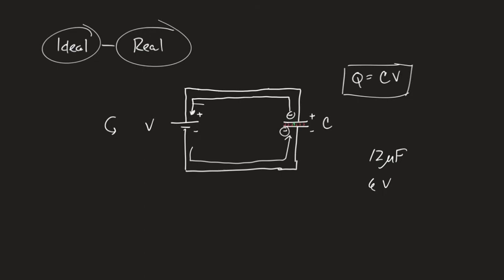Is it blue because of the chemical burning? Yeah. Generally. And the dielectrics that they tend to fill these with and the electrolytes that they fill these with are toxic. So if you see the blue smoke, it can kill you. So please stay away. It's usually pretty bad, or it's usually a carcinogen. So generally, whatever the power rating is, you can't exceed it because it creates an electric field too high.